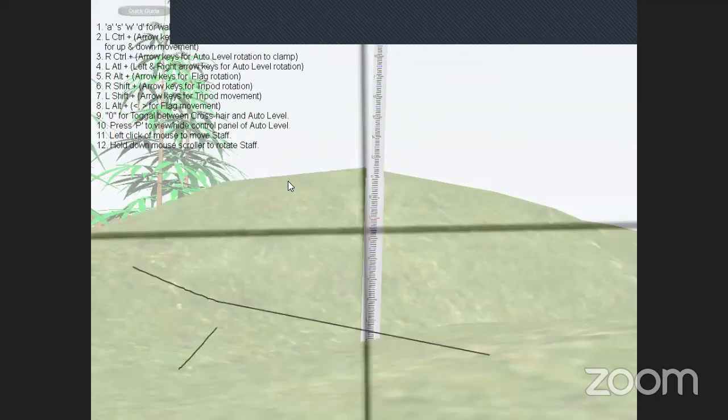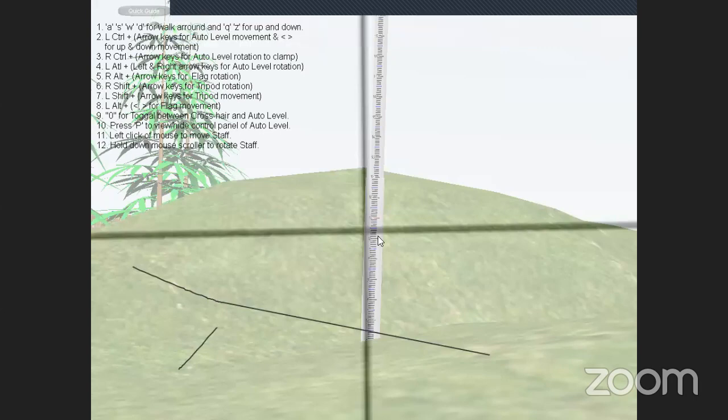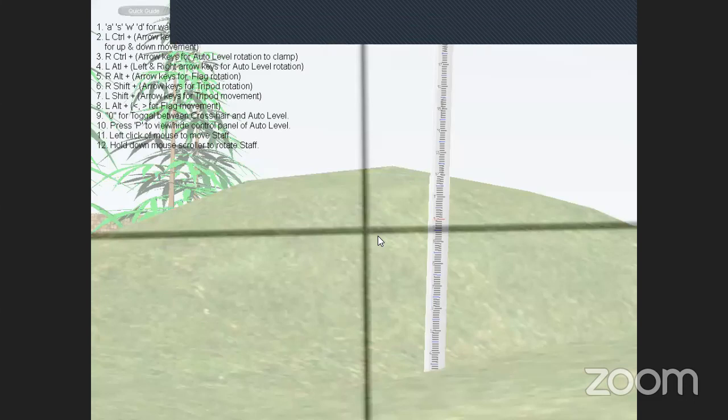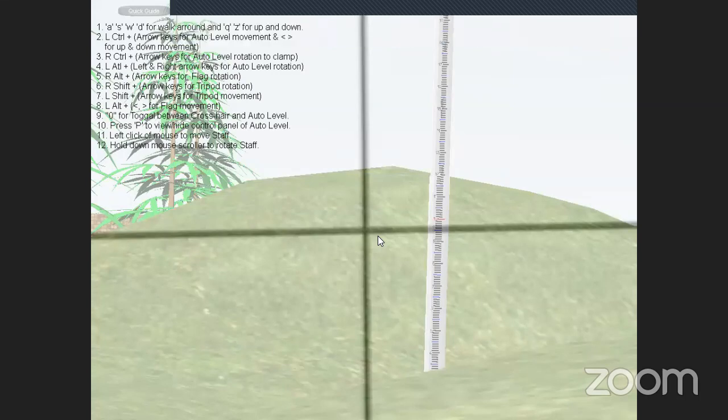See, now it is visible. It is about 0.95 meters. Yes or not? 0.95 or 0.97 meters. Yeah, 0.97 meters. This is an intermediate sight to you. C also is an intermediate sight, 0.97. Okay.